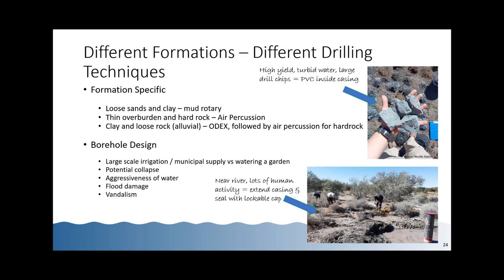And this is specifically needed when we've got problem formations like lots of clay, which suck onto your drill bit, or loose rocks or pebbles in an alluvial area that can bounce around. And if, for example, they do normal air percussion in an area like this, you can end up getting casing tearing, or the driller can take 3 or 4 more days on site, which you don't really want. It becomes a real mess.